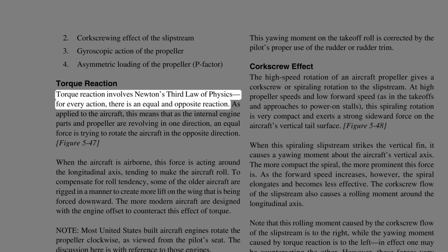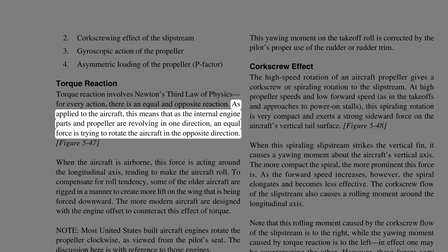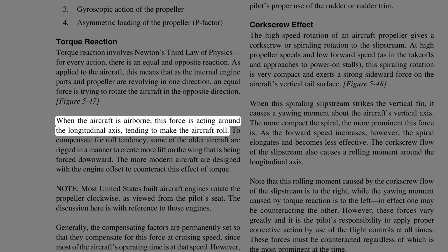Torque reaction. Torque reaction involves Newton's third law of physics: for every action, there is an equal and opposite reaction. As applied to the aircraft, this means that as the internal engine parts and propeller are revolving in one direction, an equal force is trying to rotate the aircraft in the opposite direction. When the aircraft is airborne, this force is acting around the longitudinal axis, tending to make the aircraft roll.